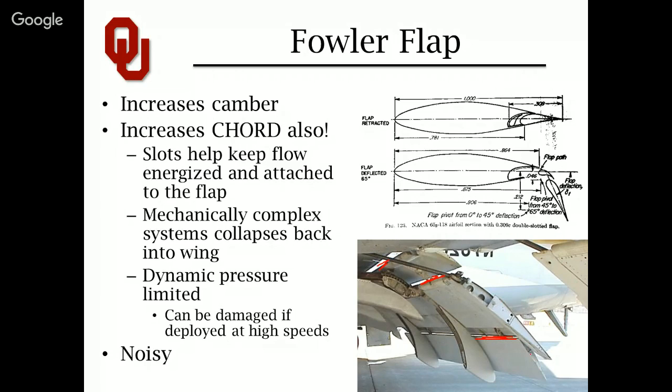At each boundary of this flap system, there's an edge, there's one more edge, here's an edge, there's a giant stick out in the flow, a giant hydraulic actuator handle. There's the back face of an aerodynamic device. Here's an open front face. They're aerodynamically very dirty. They disrupt the air and create everything but smooth airflow over those aerodynamic devices. What this generates is noise.